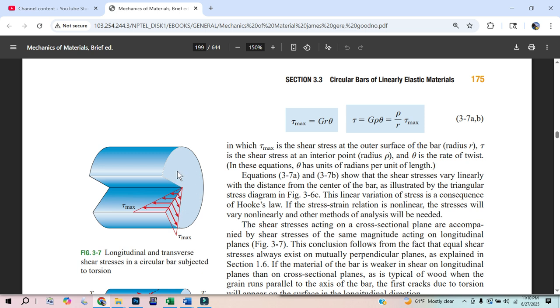So now in the center, we're going to have 50 molecules that can take 1 pound each, tangentially, but they're only a distance of half the radius. So therefore, which is half of an inch in our case, because we're having a cylinder of a radius of 1. So we have 50 molecules times a half times a half. That's 50 times a quarter. You know what I mean? That's 12.5. So this can only provide 12.5 pounds of torque.